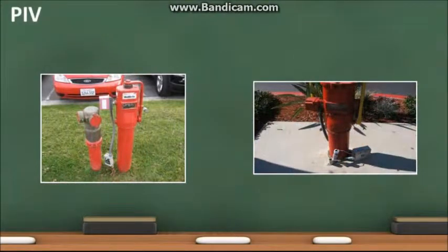In the photo on the left, the cover for the tamper switch is missing. In the photo on the right, the J-box has detached from the conduit. It is important to note that chains and breakaway locks are not required when there is a tamper switch installed, as in these photos.